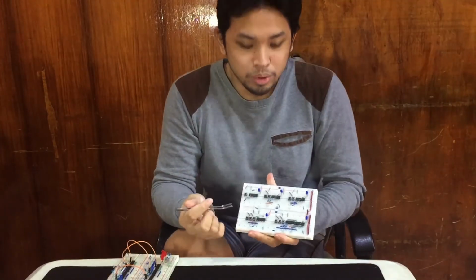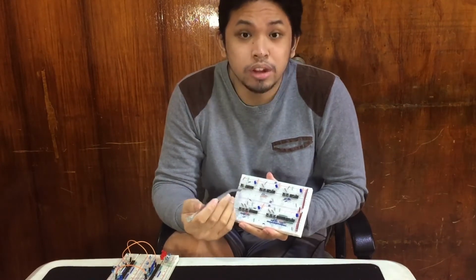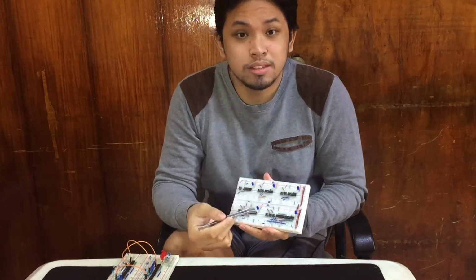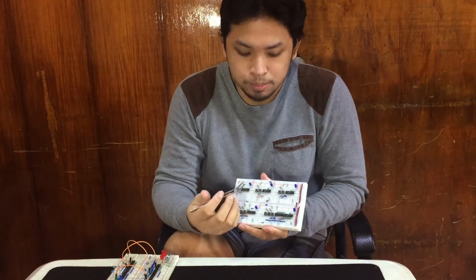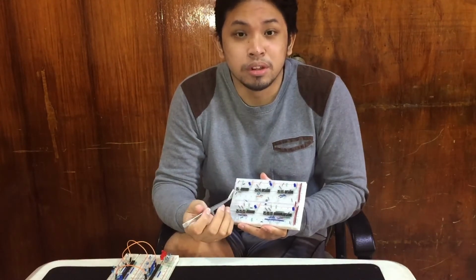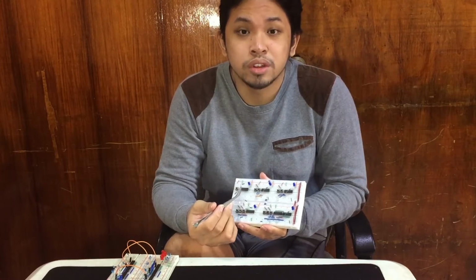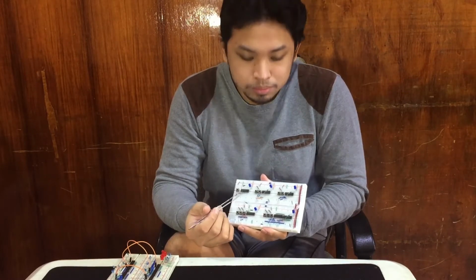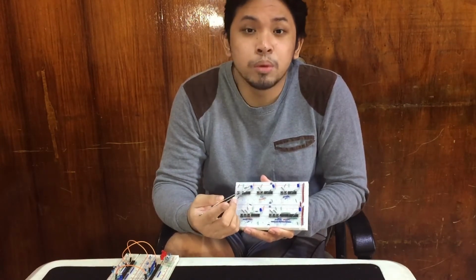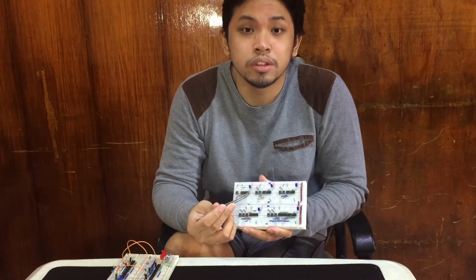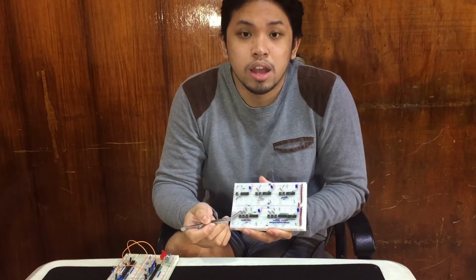For the next part, we have a combination of the 7408 and the 7432, which has three inputs as well: input A, B, and C. Input B and C are both connected to the input of the 7408, and input A is connected to the input of a 7432. The output of a 7408 is connected to the input of the 7432. Now, as we know from the previous parts, 7408 outputs 1 when both inputs are at 1, and 7432 outputs 1 when either or both inputs are at 1.